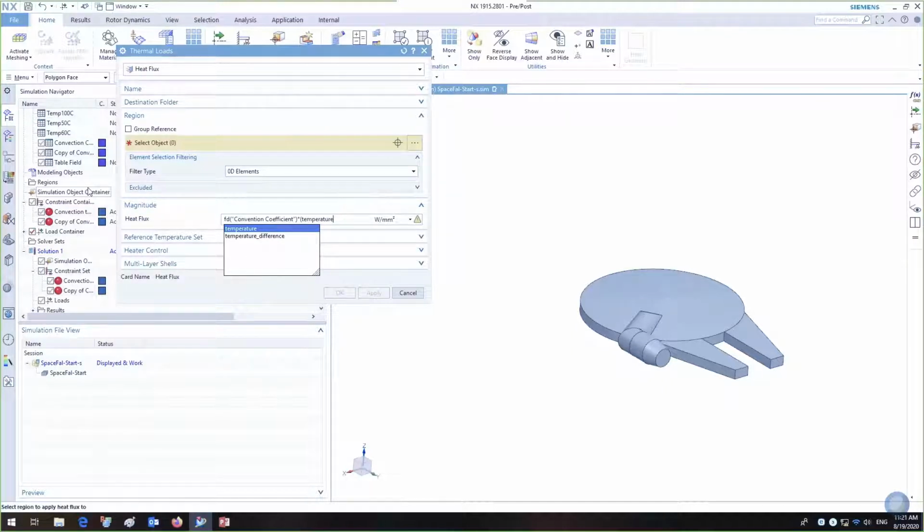So we want to use the temperature of the surface. To do that, we will use the symbol-like expression temperature, which is an expression that gets evaluated at runtime. So this will change as the run evolves. The solver will understand that to be the element temperature that you're selecting, minus the field that we just imported. So once again, we'll use the FD function to call that temperature versus Cartesian field that will get evaluated at runtime by the solver.